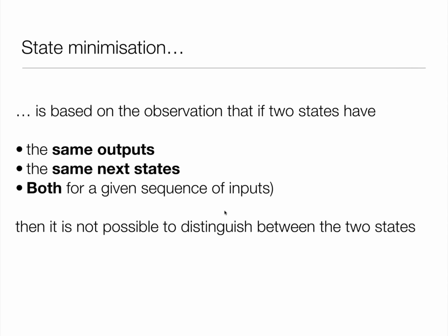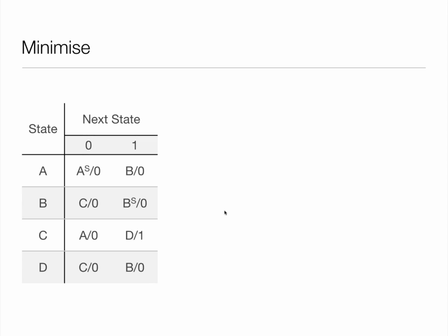So let's actually look at that. So let's look at this Mealy machine state transition table. No output column here because the outputs are embedded in here now. And that's what makes it possible to sometimes reduce them further. So the S just means self. All right, so 2 selves are equivalent, as we discussed last week. So A goes to A with a 0 input, and to B with a 1 input, etc.